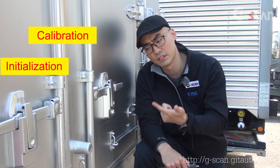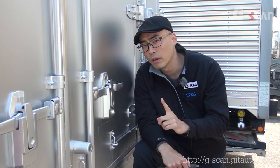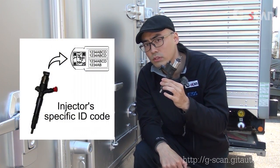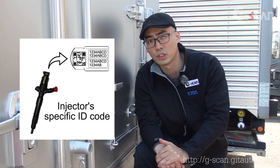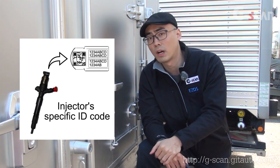Other than erasing and learning function, there's calibration, initialization, reset, and coding functions. One out of many different examples will be injectors. When you replace injectors, you have to code or write specific injector's ID code into ECU for correct fuel quantity adjustment. Let's see some special functions of Mitsubishi Fuso commercial trucks.